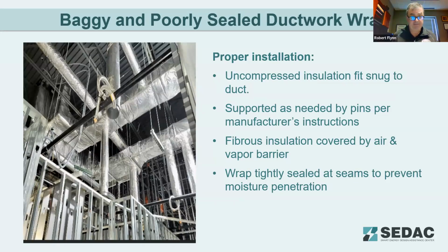And this one that Sean is showing here, the last one had a different jacketing. It had ASJ jacketing, a little bit higher density, while the ductwork in this picture is more of a blanket insulation with a lesser density. However, the same thing applies. You can see the hangers are underneath the insulation.